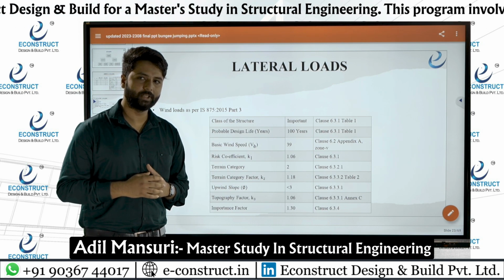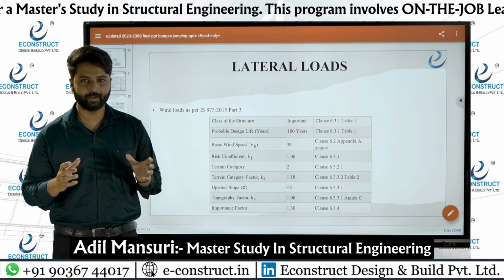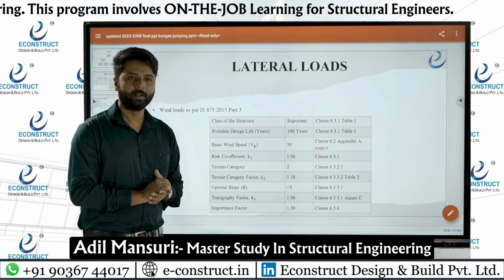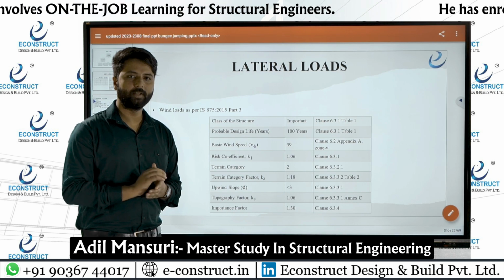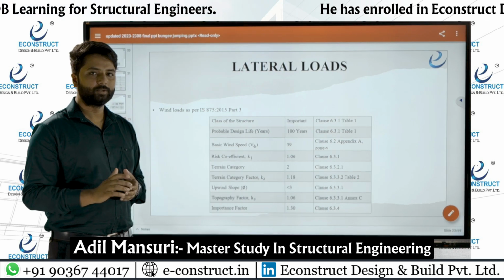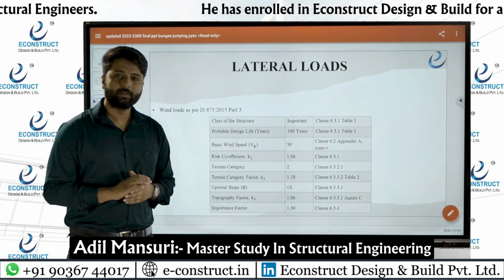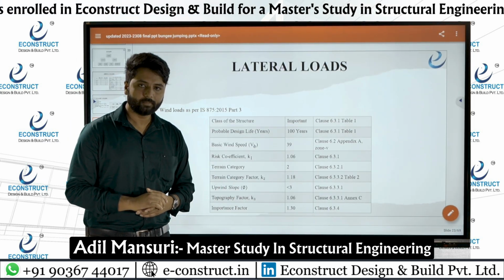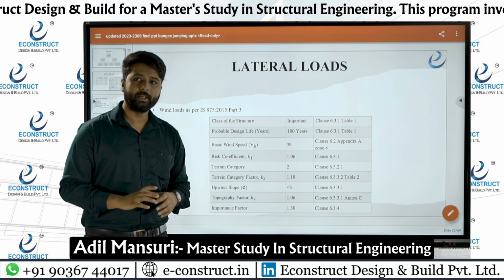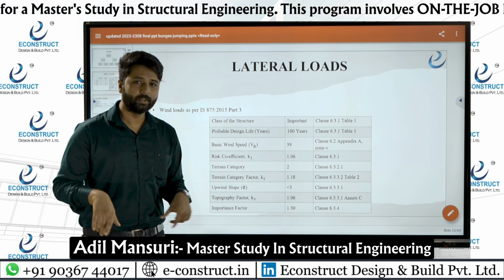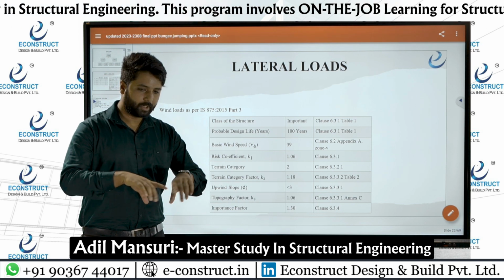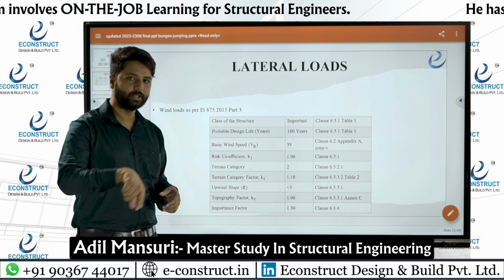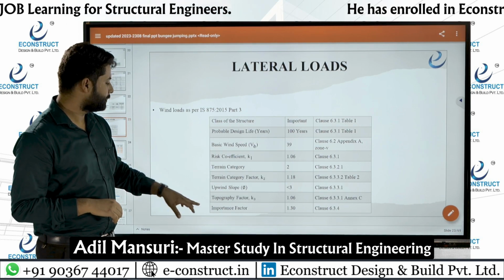The major challenge we have faced in this project is to control the big cantilever portion and also the lateral displacement due to wind forces. So for this project we have considered importance factor like 1.3 as per the code. Basically it is situated in Goa and it is coming in the coastal region, under the 200 kilometer periphery, and it is nearby coastal.